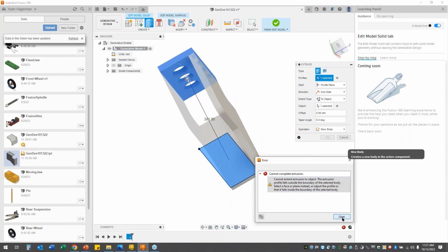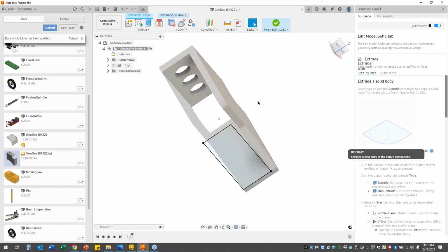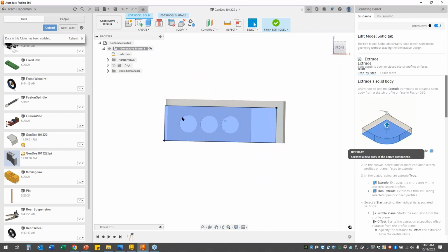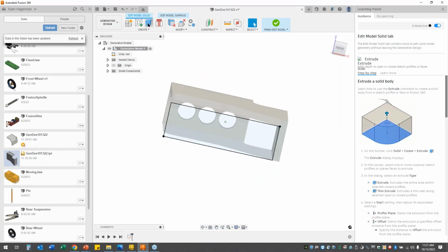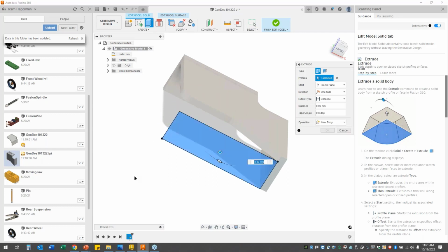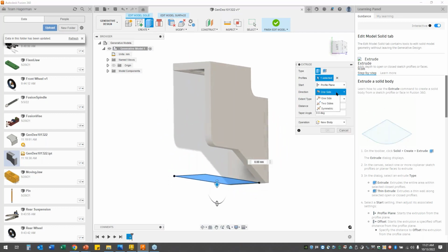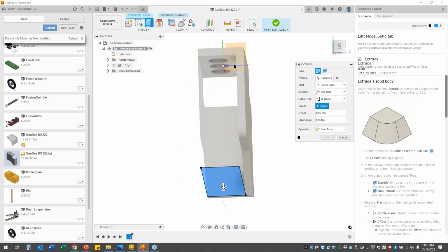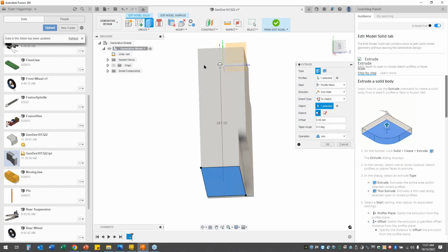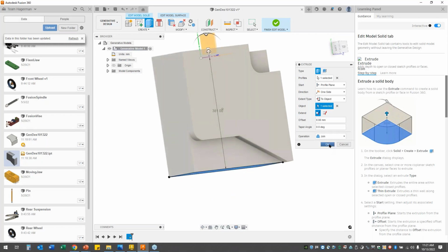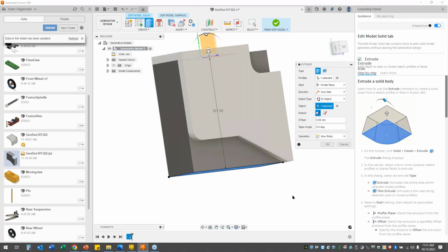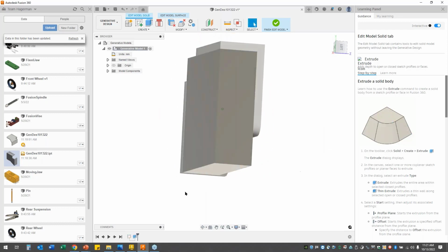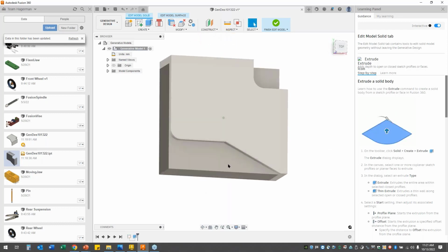Outside the selected body. Well, let's cancel that and look at it one more time. We've got our sketch. No big deal. We're changing our direction, or rather our extents, to object. And we're saying right here, there we go. Now it gives us a nice preview. I don't want to join that. I want to do that as a new body. So we'll select OK.